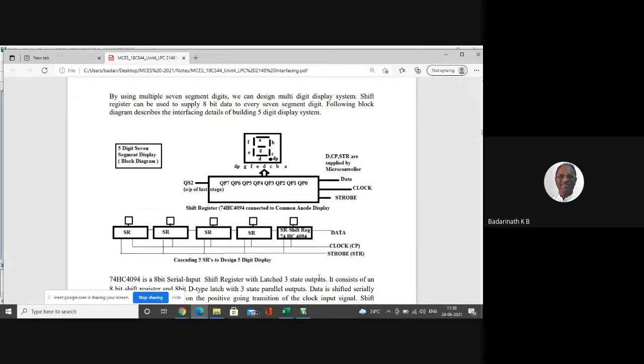In a lot of industrial applications, along with an LCD, they also give a 7-segment display because it's easy to look at and perceive the numbers. Many times in industries, we use numbers for indicating certain actions, such as a number changing, or an operator can set a particular number. So it's easy to add a 7-segment display along with an LCD. That makes the 7-segment display the de facto standard when you want to see certain things from a long distance.